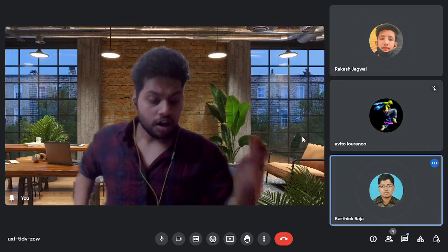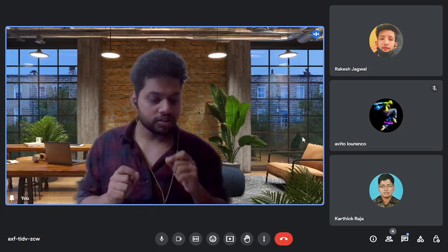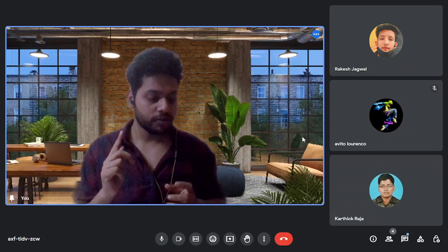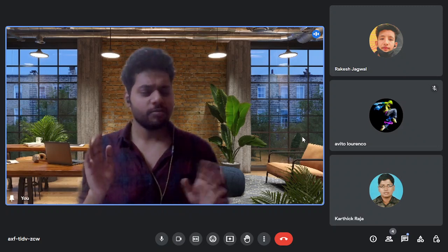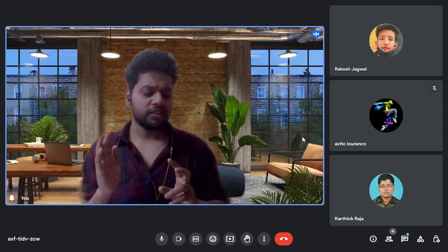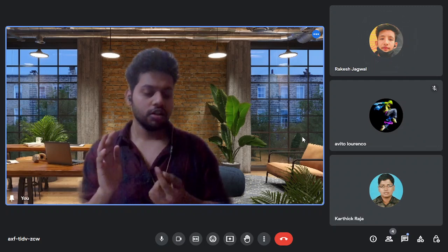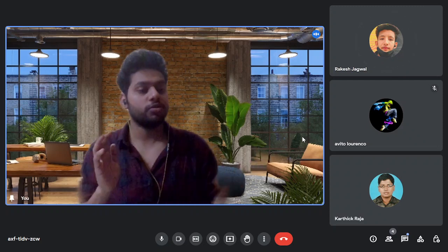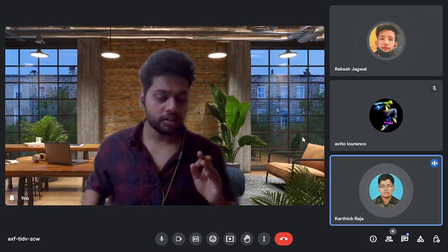A thermocouple is a temperature sensing device that consists of two different metals connected at one end. When the junction of the two metals is exposed to different temperatures, a voltage is generated. Voltage and EMF are the same thing, no? Better to say voltage here, okay? Which is proportional to the temperature difference. Proportional, not equal. You just said equal.